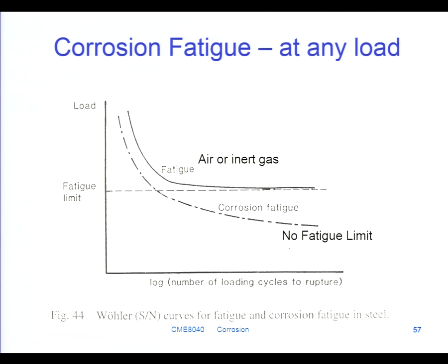You've got to think about how the component has been manufactured. Does it have any additional residual stresses in it? And are any of them tensile? When you get a component that has a residual stress in it, there's always a balance. The component is stable, it's not moving. You made a pipe, it doesn't change shape.